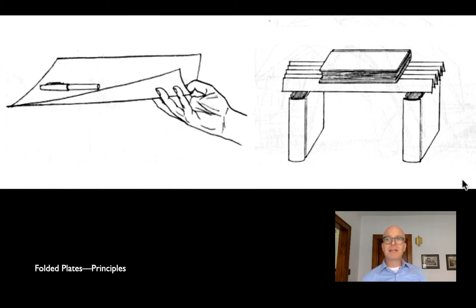What we're missing in this drawing is that edge stiffener, or the horizontal beam, the stiffening structure that's going to keep the folded plate in its geometry. That's going to force it to stay in the structural geometry that we want.